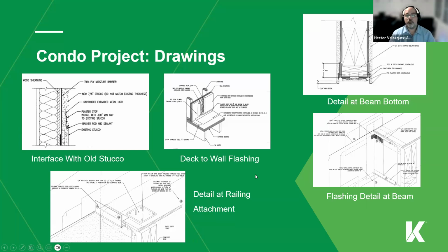Keep in mind that the waterproofing is not just on the deck. It's a typical requirement for a waterproofing system that it has to go up the wall. Typically we go 4 to 6 inches maybe, but it has to be on the wall. Then you put on your stucco system. So it's behind the stucco system, because the stucco is porous and will let water go through. So you want to hold that, especially on the corner sections.